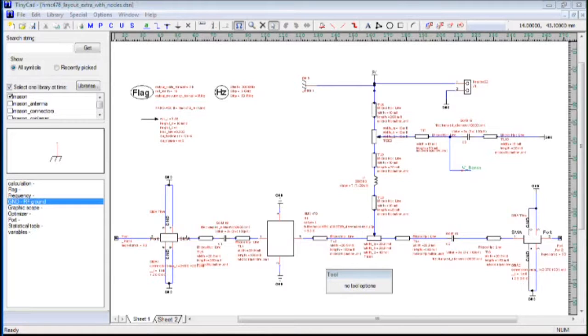And then these components, again, are not part of the RF simulation, so I just put in a package, not an actual file or primitive parameter for this. But here, I just have these dumb footprints. These are footprints that the layout software I use knows what a DIP18 is. It knows what a 0402 is, but it's not part of an XML file that includes how these parts get connected in, what the orientation is relative to their neighbors. So this is just going to show up in the layout. We're going to have to place these by hand. But for digital parts, that's pretty much what you want to do.